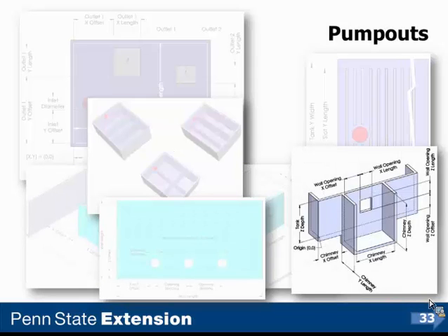You can also incorporate pump out annexes on any one of the side walls or end walls. You can incorporate multiple pump out annexes. You can locate the manure pit ventilation fans in the top of these annexes as well.